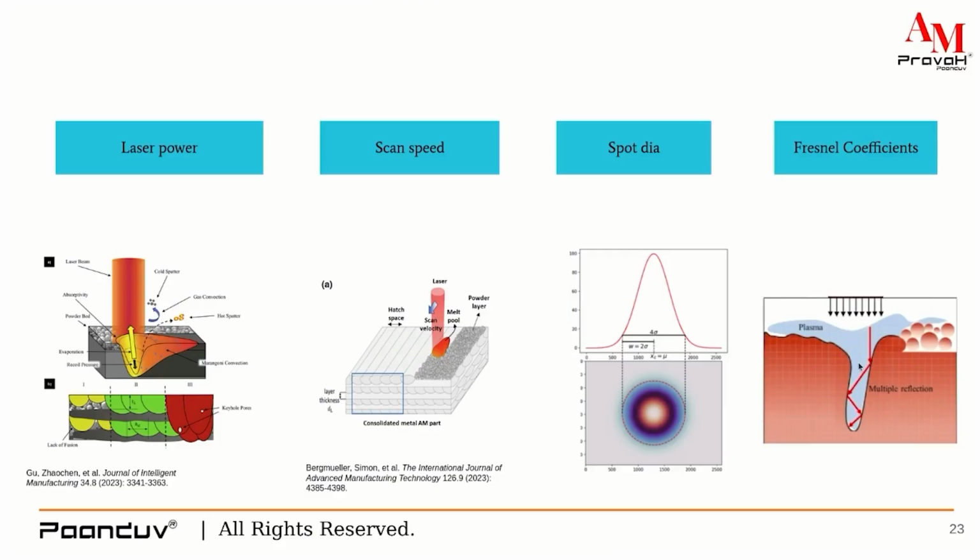Chamber pressure, again, it is a very important parameter that people have not identified yet. When you have an ambient pressure in your system, you can get even higher keyhole porosities, because the vapor has a tendency to go from higher pressures to lower pressure. When these pressure differences are higher, the vapor will be taken away more efficiently.